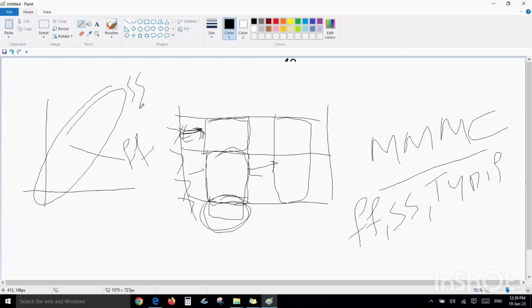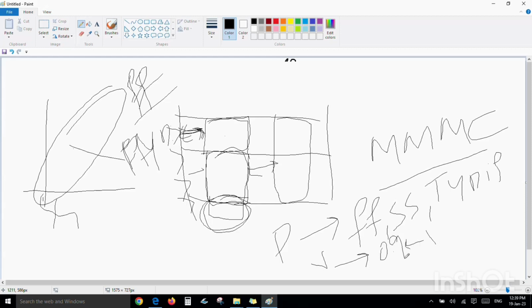The typical corner is in the middle, this will be SS, and this will be FF corner. We need to close my chip at all the corners. P is the process corner, and V is the voltage level. If my operating voltage is 1 volt, then 10% from this will be 0.9 and 1.1, so 10% corners we used to take.